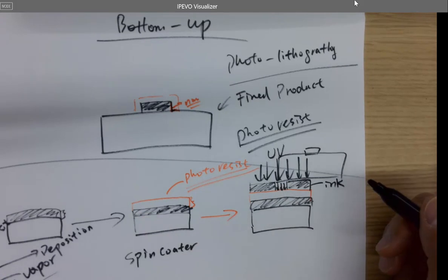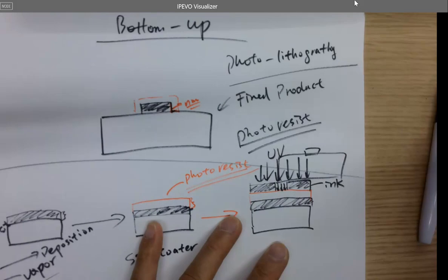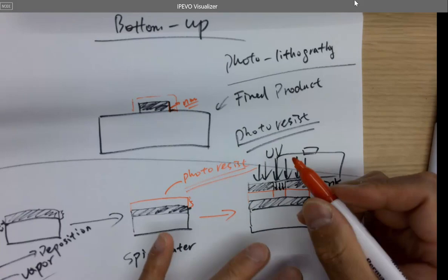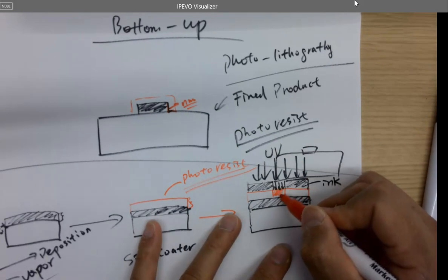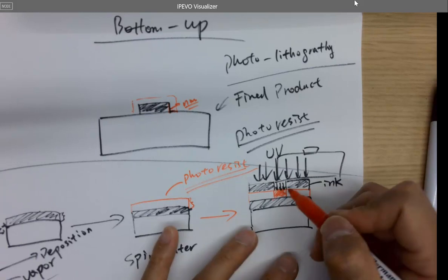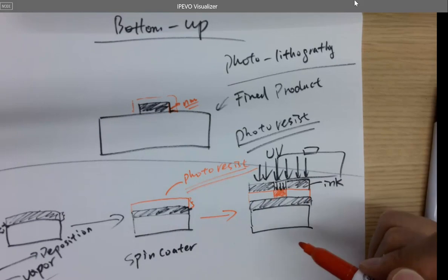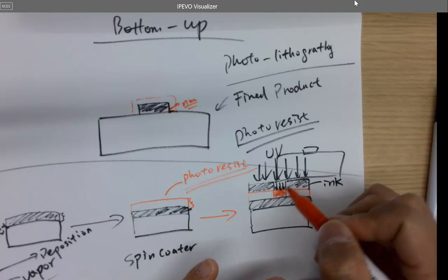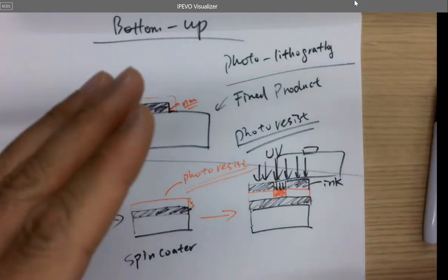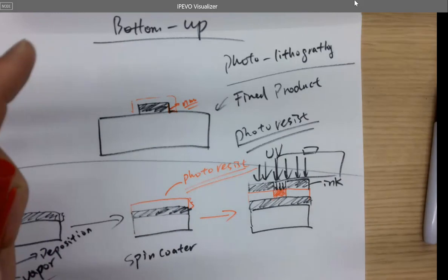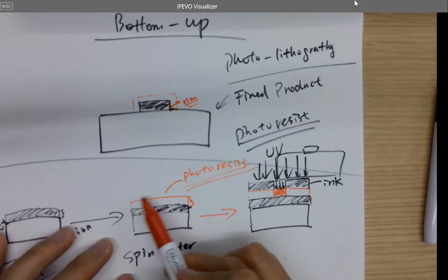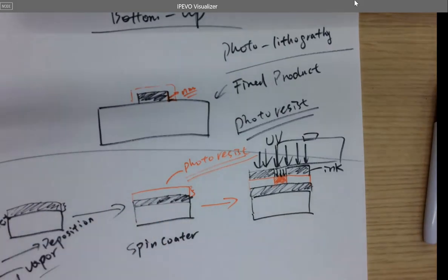Okay. So this part of the photoresist is photosensitive. After being exposed to UV, it's getting cured. The texture just changes. And because the mask is not like honey you sprinkle on it, it's just a glass plate or a plastic film, you put it on the top of this thing, right? And then you expose it using UV, so you can remove it just by hand, for example.